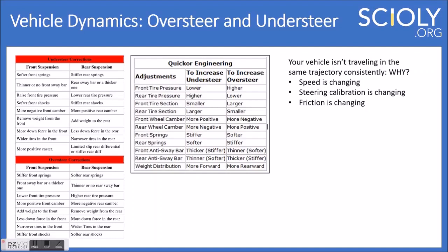So that could easily be another reason. From there on, we stopped using belt conditioner to clean our wheels. We went back to water because we didn't want to see such inconsistencies. Even though it was getting better acceleration, we wanted to make sure that whatever results and data we were collecting were consistent, and that we'd be able to repeat this at tournaments.